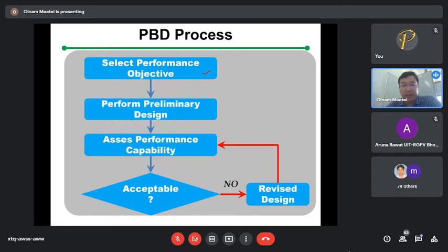Accordingly, you perform the preliminary designs. For India, use IS 1893. For America, use the building code. For Australia, you can use the Australian code of practice. New Zealand code and the Japanese code. Different countries have different codes, and they have different design criteria. Logics are the same, but the values are different. Don't think the American code, European code, and our codes are the same. The concept is fine, but the values will be different.